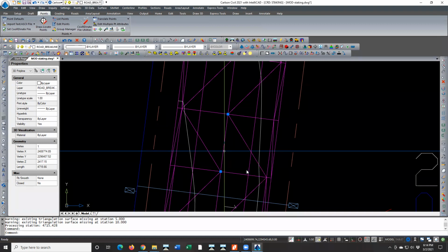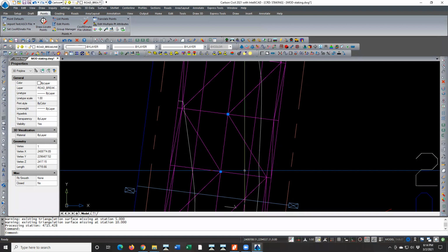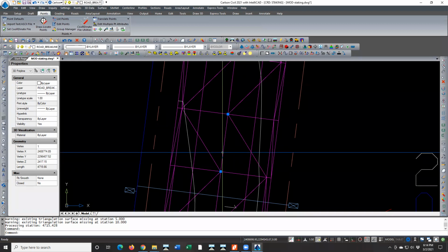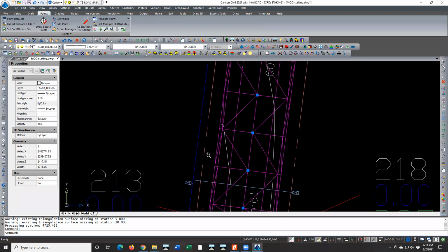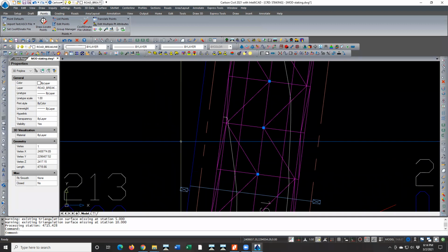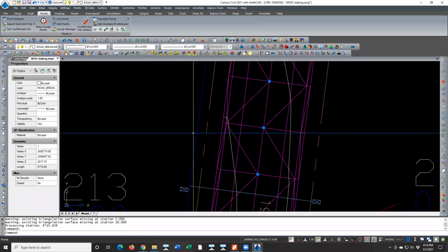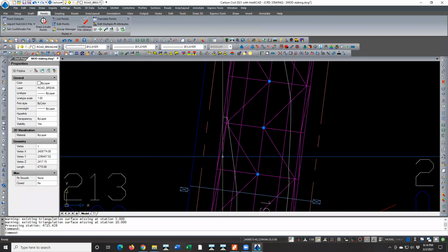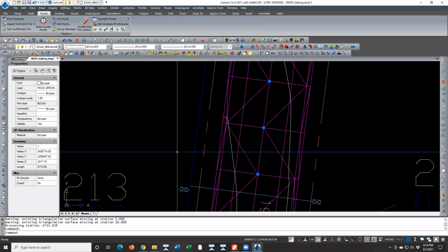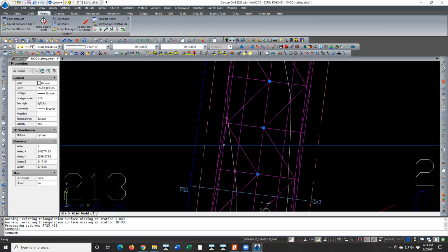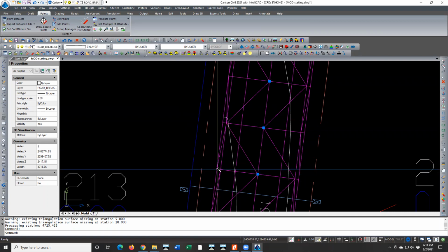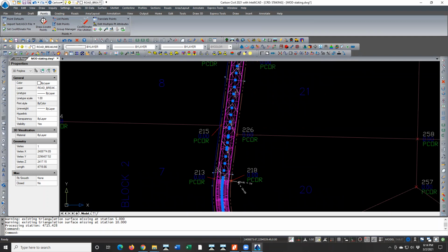Now you can suffix those layer names with the actual grade point name, so that might be center line or whatever subgrade name. It would also come over here and do everything, including the 4:1 side slopes to catch your cut and fills. It will catch those subgrades where they run out and draw your daylight. Then you just isolate them by layer and build those as separate surfaces.